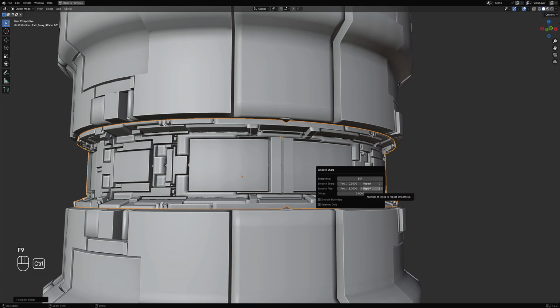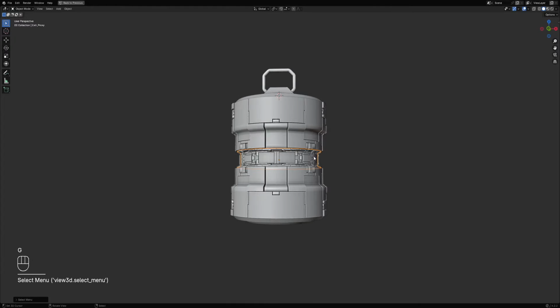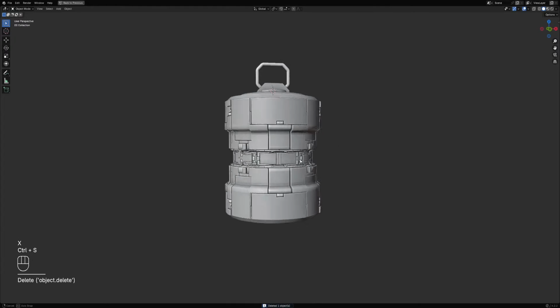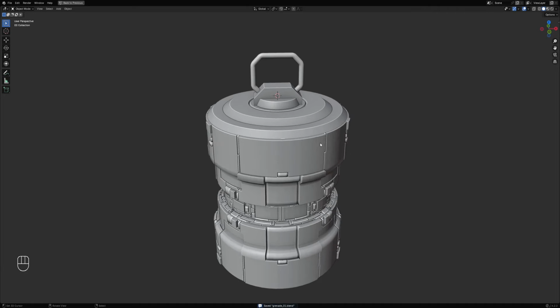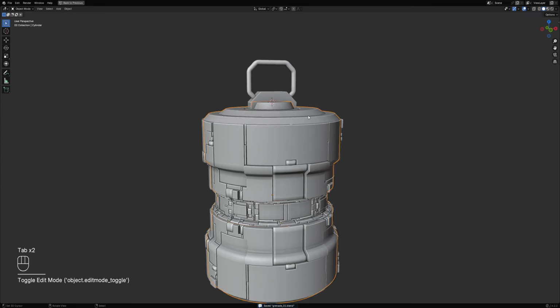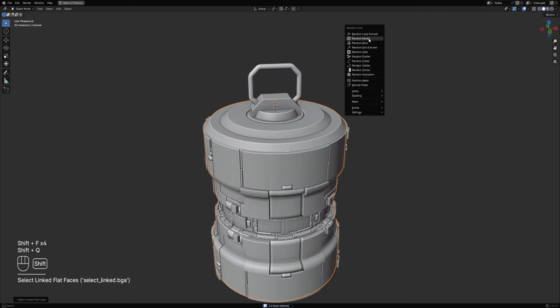And yeah, this one. There we go. And extract proxy, delete that. We don't need that anymore. So only delete that if you don't need it anymore, because you might still use it to layer some random details again later on. Okay, so this part here, Control Shift A to deselect everything, Shift F, and random panels again.